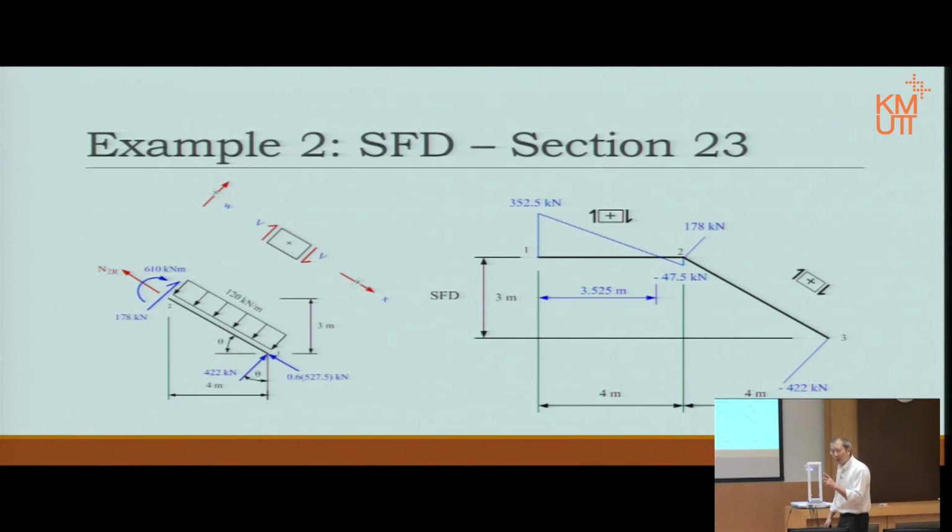Again, the total force is not equal to the shear force. The total force is equal to the change in shear force. And it is a straight line, because it changes the same amount every single distance, therefore it is a straight line change. And again, there we are. The same idea which we calculated the first time.